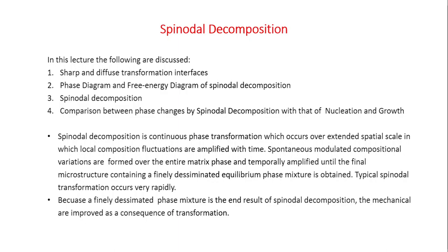Spinodal decomposition is a continuous phase transformation which occurs over extended spatial scale, in which local composition fluctuations are amplified with time. Spontaneous modulated compositional variations are formed over the entire matrix space and temporally amplified until the final microstructure containing a finely disseminated equilibrium phase mixture is obtained.